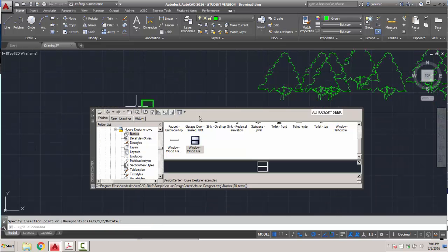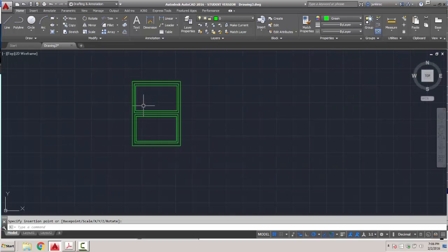We'll zoom into it. Let's go ahead and close this out and see if it measures. So here's my measuring tool. We'll just measure distance. This should be 36, which it is, and this should be 48. So it's a scalable cell. So if we have specific size windows, we can take that cell. Let's imagine we had one that's 52. Let's see if this works.